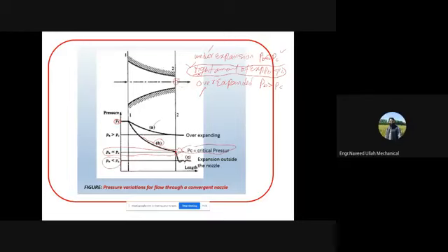Here you have the value PC. But obviously the exhaust is going to the atmosphere, so the pressure should be the same. So from this PC there is further expansion, outside the nozzle. That is your under expanded case. The expansion is there but not totally inside the nozzle; there is some expansion outside the nozzle. It is even written here, expansion outside the nozzle, so that is your under expanded case.